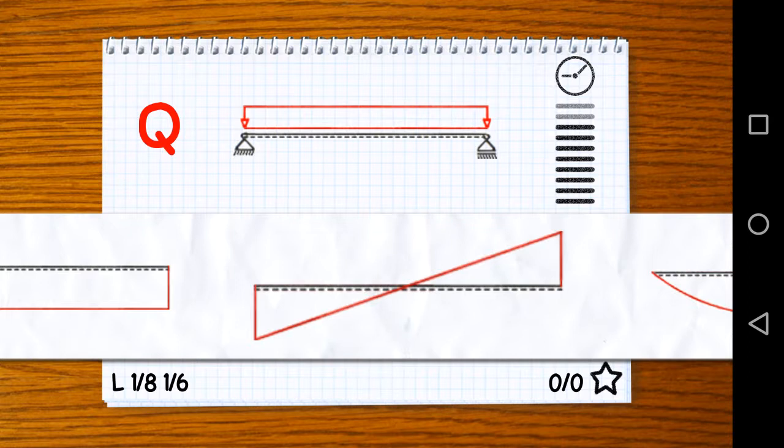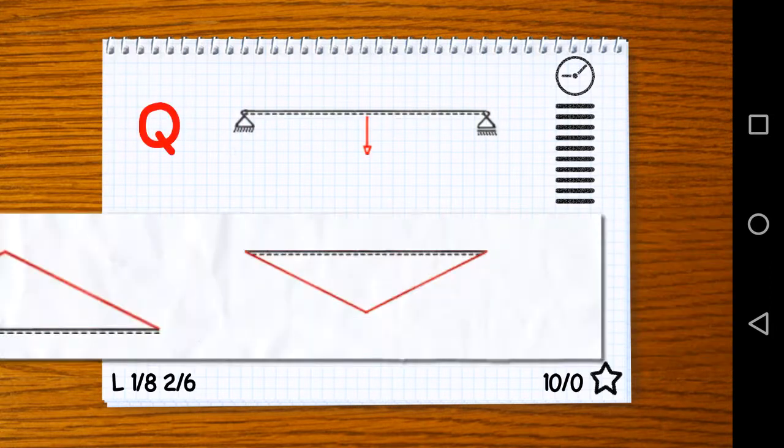On the left and the right support, we're going to have forces applied in the upward direction. So within the beam from the right to the left, we're going to have a jump on the right, then moving downwards linearly in the direction of the load, and then a jump upward at the left pin support. So this distribution in the middle is the right one.